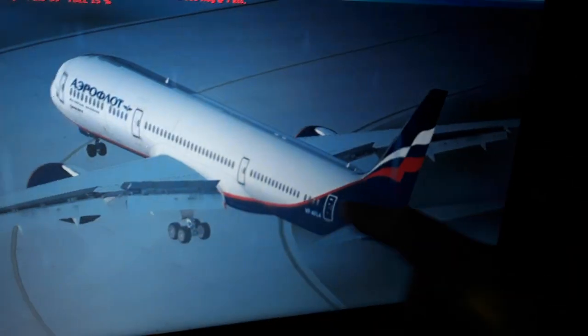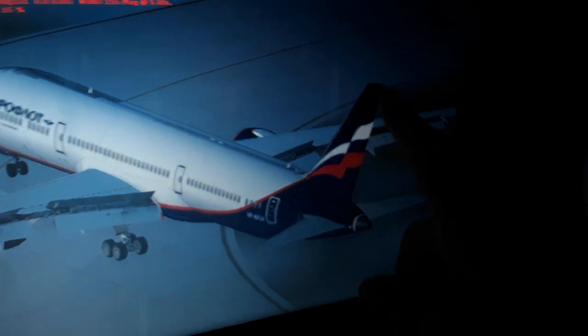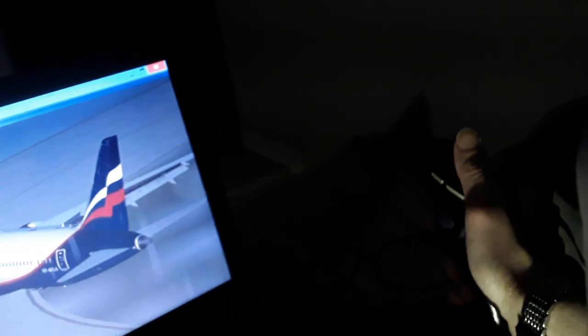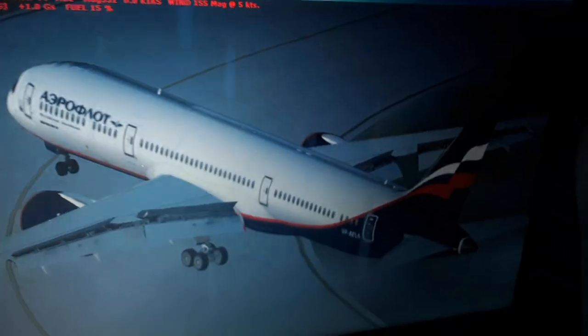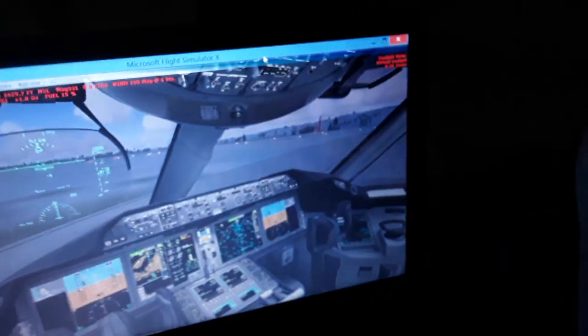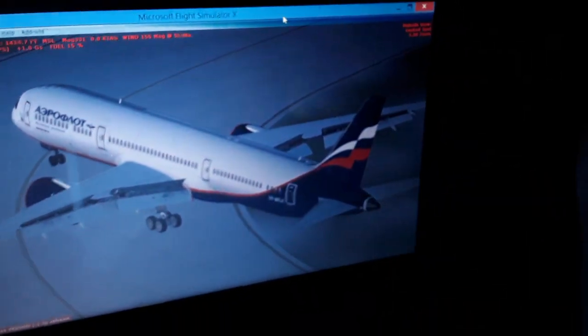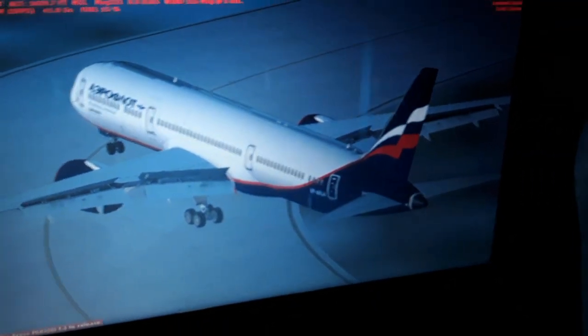So above 80 knots, or 144 kilometers an hour, the airflow becomes aerodynamically effective in the rudder, and the forward nozzle will be locked to 0 deflection or small deflection like half or 1 degree. This is how to use the yaw axis over here, the rudder pedals. So you take off only with the rudder like 250 kilometers, also you land, and then after you slow down, the nozzle becomes activated.